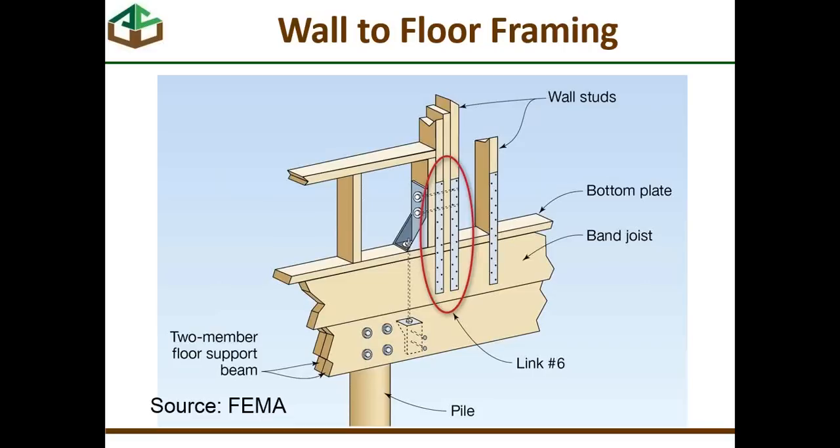When you go and use the wood frame construction manual and look at the loads on uplift from the effect of a roof in 1 story or a roof in 2 stories, the loads have been adequately reduced to cover the weight of the floors and the walls that are attached to them. So just recognize that you are using the loads that have already been reduced, if you will, because you have the added benefit of using the weight to resist the uplift. So using the loads out of the manual should get you the correct uplift answers here when you look at this particular connection.